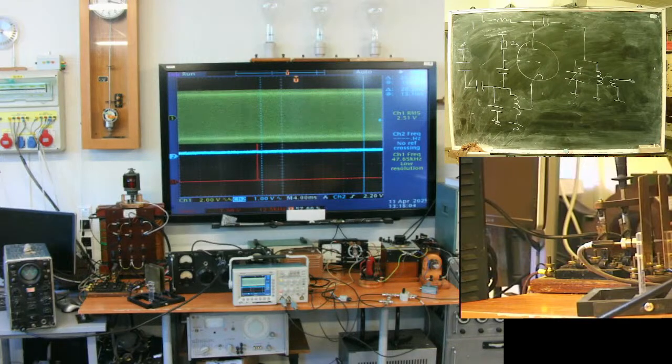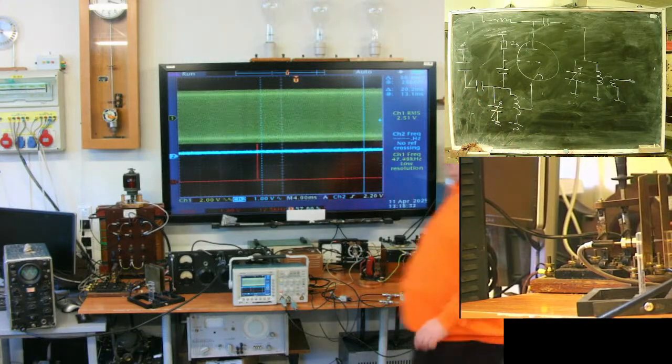In one case, in the case of both sources, it's a capacitance against ground. So I'm adding additional capacitance. This one is variable, so I can adjust zero difference between two generators. But if I introduce something here, it will change the overall capacity of this contour, and the frequency will shift. What can I do?